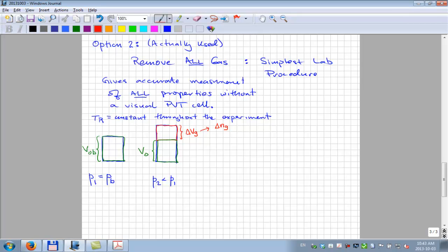Typically, when they take the gas out, they put it through a gas meter at standard conditions, so they'll know that. They'll certainly know the molecular weight of that gas, sometimes expressed as a specific gravity. You remember that's just the ratio of the gas molecular weight to air molecular weight. And optionally, they may measure the composition of that removed gas. Sometimes they do, sometimes they don't.